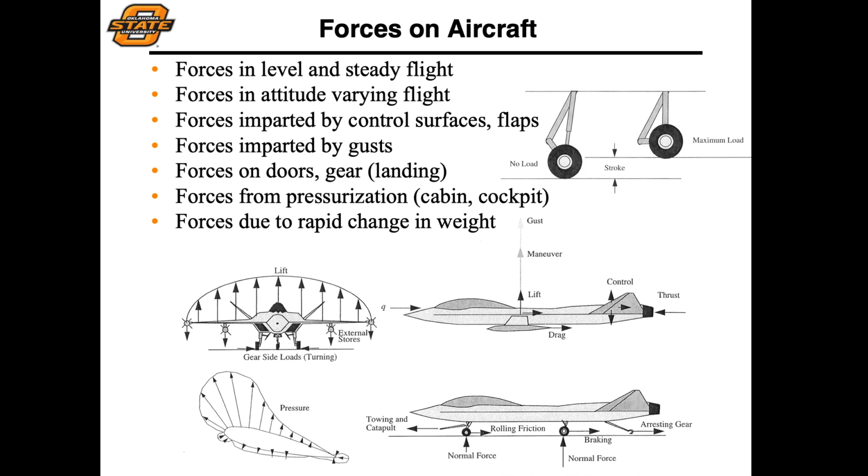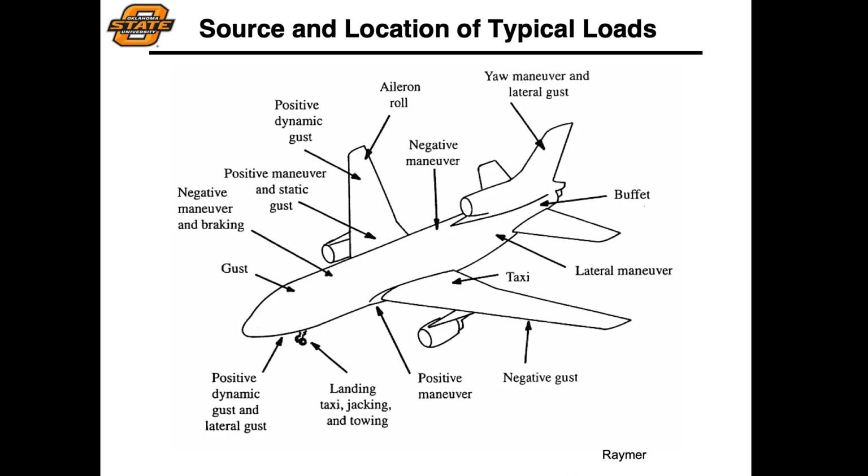Now, as we mentioned previously, a lot of the forces that we see on the aircraft are primarily due to unsteady loads. Even though we'll be thinking about steady loads in design consideration, that's really the lowest and minimal type of loads that we're going to see acting on our aircraft. So we almost always design the structure of the aircraft around unsteady or dynamic forces acting on it, because those are going to be the most stringent loads that we're going to see for our aircraft during flight.